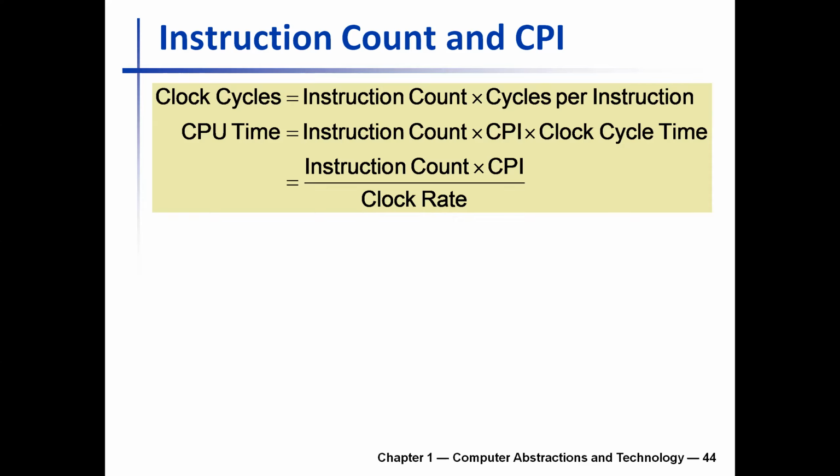It's an average that we define for a computer processor running a particular program. Also, you should understand something here. When it comes to microarchitecture, there are two types of processors. You will learn it later, but I will give you a very brief overview. There are two types of microarchitectures when you implement an ISA in actual hardware: single cycle processors and multi-cycle processors.